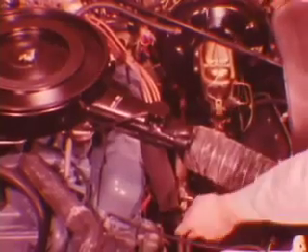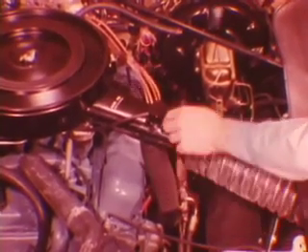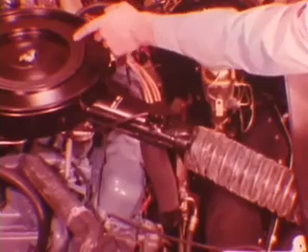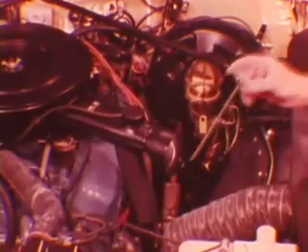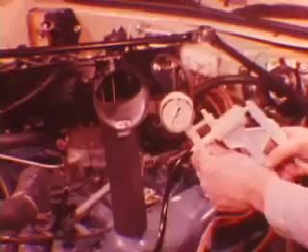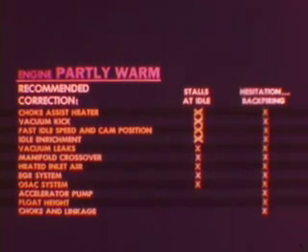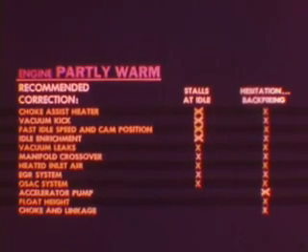In all these cases, make sure that the heated inlet air system warms the incoming air to help the cold mixture atomize for good drivability. Check the air door operating temperature to make sure it does not open to direct inlet air too soon. Cycle the air door with a hand pump. The choke assist heater, vacuum kick, fast idle, and idle enrichment systems must all operate properly.